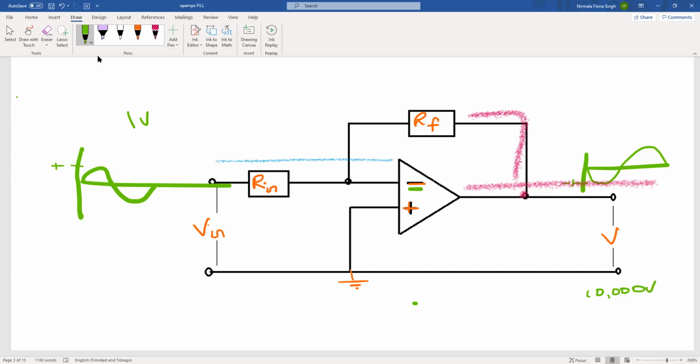Usually your amplifier has a source voltage, that's our VS. Our amplifiers are built such that they do not take voltages larger than the source voltage. So that means I don't want to feed back a very large voltage into my amplifier because I will blow my amplifier. There's very fine circuitry inside of my amplifier. It's meant to increase my signal. It's not meant to operate with a very large current.